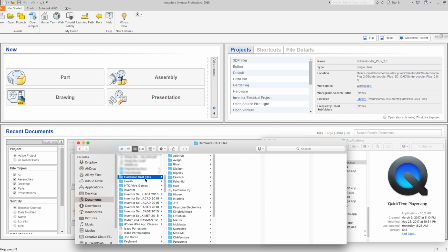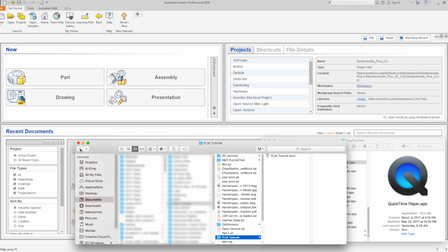The reason you want it separate is because if you had everything in your main project folder, and later you want to make another product, all your screws and washers are going to be in this other project folder, and it's a very hard time trying to link them together to use the same parts between projects. You want to separate them out, so you don't have to keep linking.